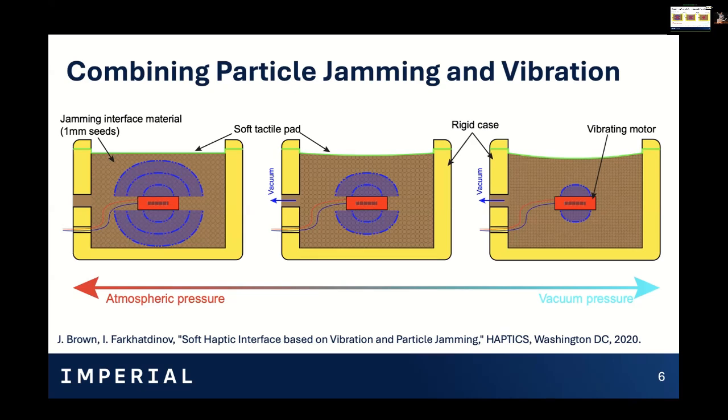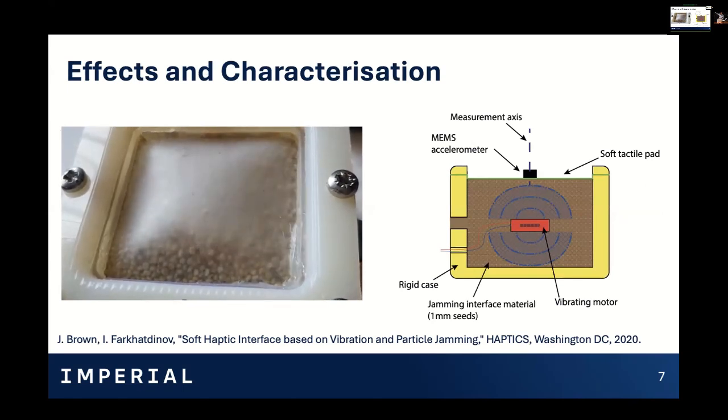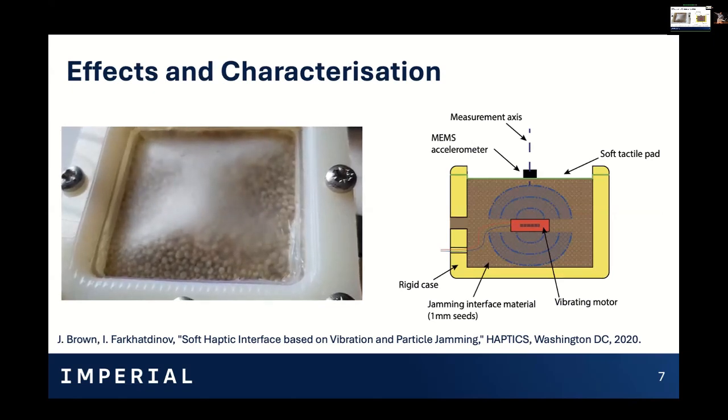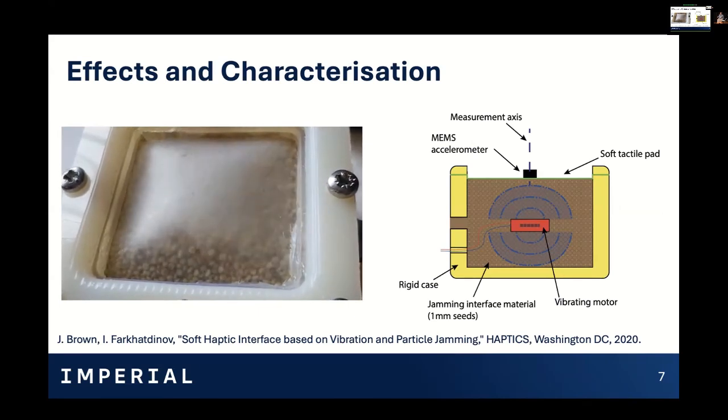But if you also embed a vibrating motor inside that, and we've got an eccentric rotating mass motor here, then you can also get the particles to vibrate, and that vibration will propagate up to the tactile surface that your user can then feel. So you can see in the video here, because it's made of silicone and sealed, you can also inflate it. We get some shape change. But then you can see when you suck the air out in a second, it's going to become a very solid, very rigid display. And then when you start to release the air pressure, the particles start to move around again, and you get that vibration effect.